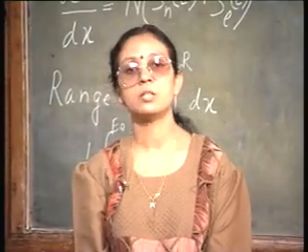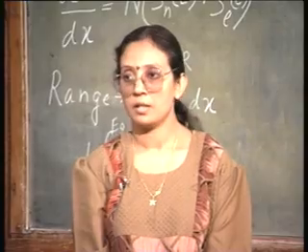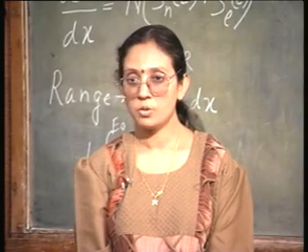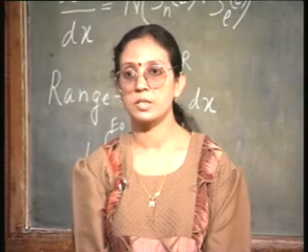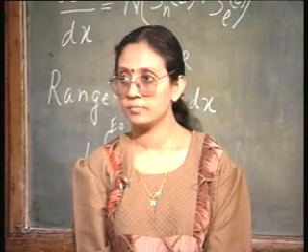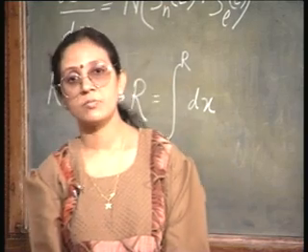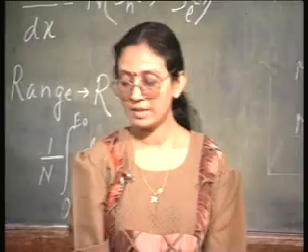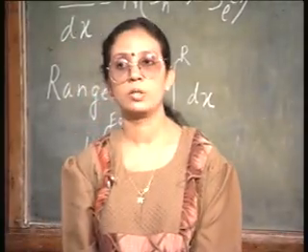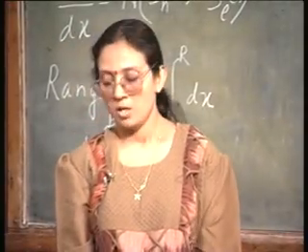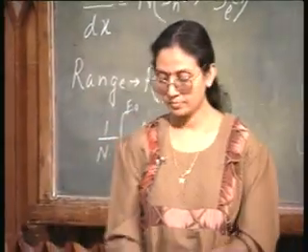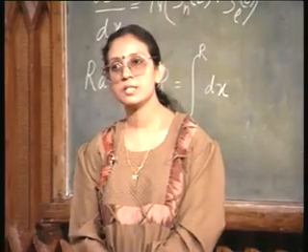See, boron is a much lighter material. Okay. So, you need much lesser energy to push it inside. Okay. So, the critical energy for boron is 15 kilo electron volt, for phosphorus it is 10 times that, 150 kilo electron volt.